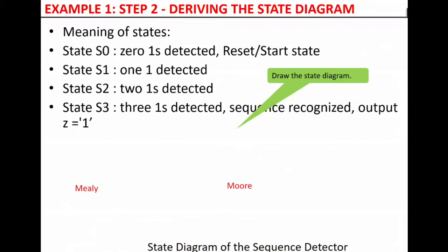Then you will have to use more flip-flops in a Moore, making it more expensive. So that is how you measure it. A Mealy tends to be cheaper because it always has fewer states than a Moore, but it's very unstable. The Moore is stable and slower. So it depends on the design parameter that you want.